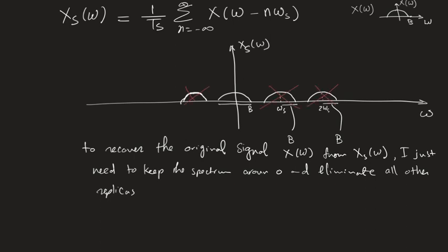That's to recover. So far, we have seen that when I sample my signal x of t, whose frequency domain representation is X of omega, with delta functions, which means in the time domain I pick values from it and throw the others, then in the frequency domain, very interestingly, the representation of the signal is repeated.